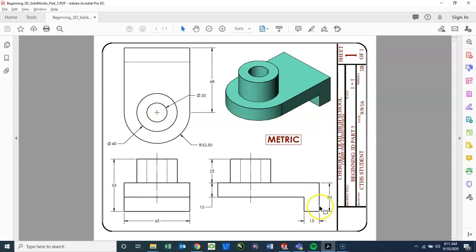Another option is to place it on the bottom corner right here in our right view, so we could position it to where the origin is there. Again, the basic shape is seen in the top view, where we could draw this rectangular shape, but it has a curve on the end here. So there's a lot of different ways we could create this part. I think the easiest way is going to be to start with the cylinder and start a sketch in the top plane and extrude down.